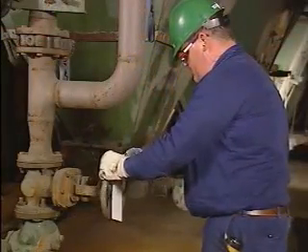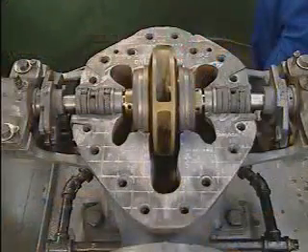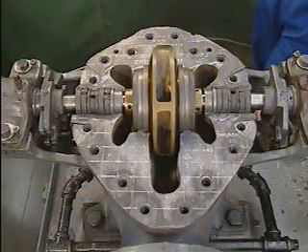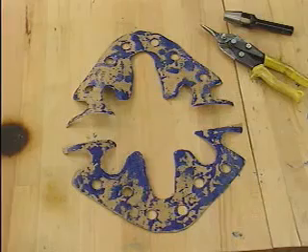This pump was properly tagged and locked out according to company maintenance procedures. The pump has been drained and vented to remove system fluid. The mechanic needs to install a new gasket between the two halves of the pump casing. This application requires a two-piece gasket made to fit each side of the casing.